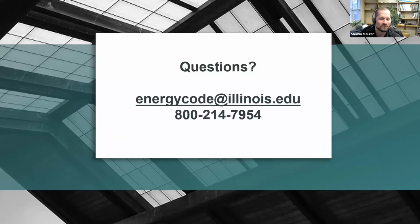All right, looks like most of our answers have come in for our poll. Share those results. So for question 1, automatic receptacle controls, looks like all of these are correct except for the commercial kitchens. You do not want receptacle controls in there. It's only 2. Classrooms and offices. The only 2 on the list. Hotel rooms, commercial kitchens, and convention centers are not on that list of automatic receptacle control requirements.